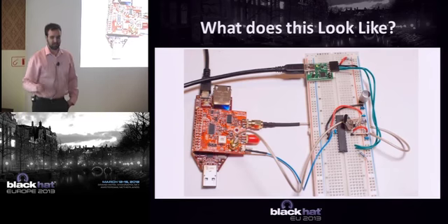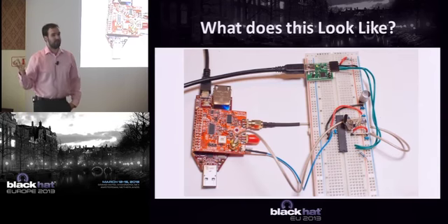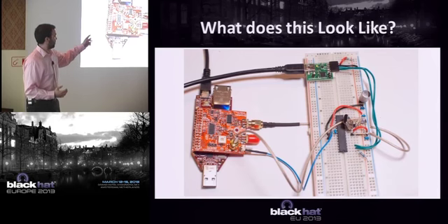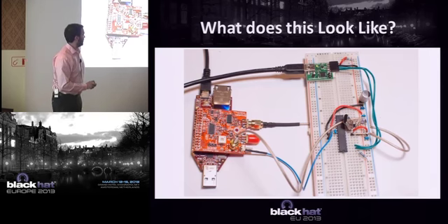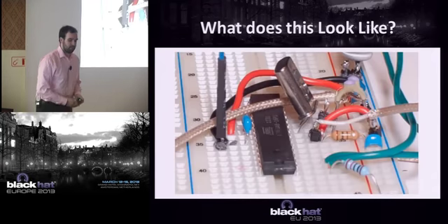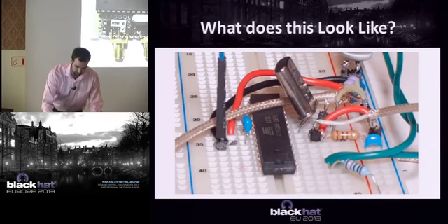So my suggestion, if you are interested in doing this, is don't buy one of those smart cards, because they can be a little trickier to find and expensive, and you need that reader. Instead, just attack an AVR microcontroller like the type used in the Arduino. You can build up something on a breadboard like I have here, and we have a crystal, we have a shunt resistor under there, and I'm measuring the power across the shunt. I have the clock frequency coming out here, and I have a little USB to UART board to send and receive data, and also for power in this case. So, very simple. These might be parts you already have hanging around somewhere in a lab.